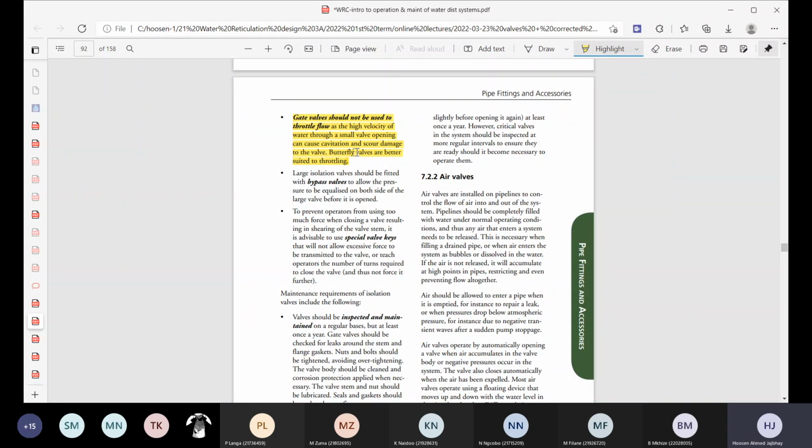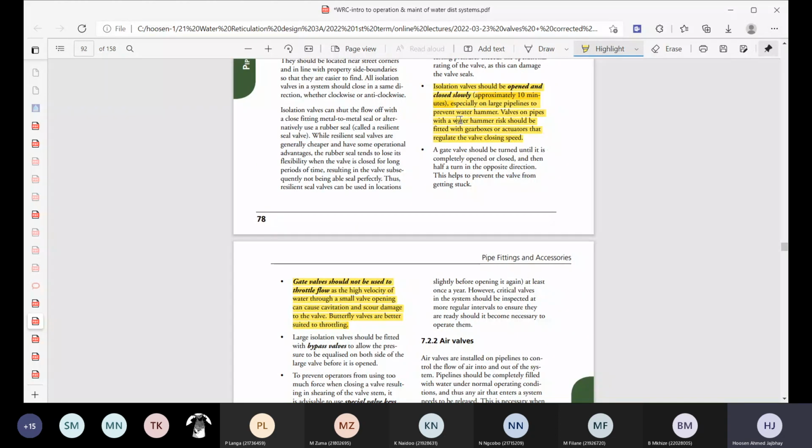I'll talk about this again when we do water hammer, if you want to know why you should not open a valve suddenly to full. Those of you that have a single lever tap at home, in your shower or bathroom, the modern single lever taps, can literally open it full in a fraction of a second and shut it fast, and you'll actually hear a loud knocking sound.